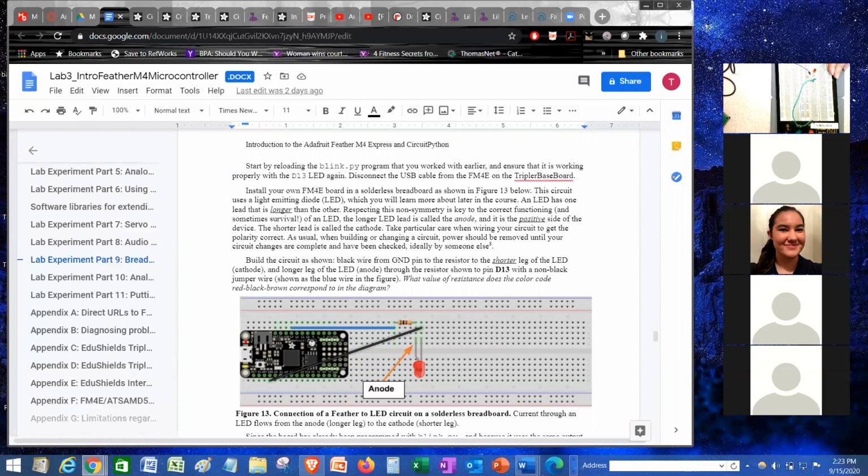As you can see here, I already put the LED and the resistor together, and this is just the wire. Keep note that the LED has a shorter leg, which is called the cathode, and that's connected to the ground. The longer leg is the anode, which is positive, and it's connected to the resistor. Remember that we connect vertically.